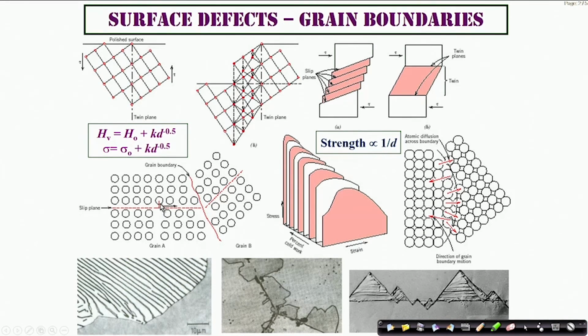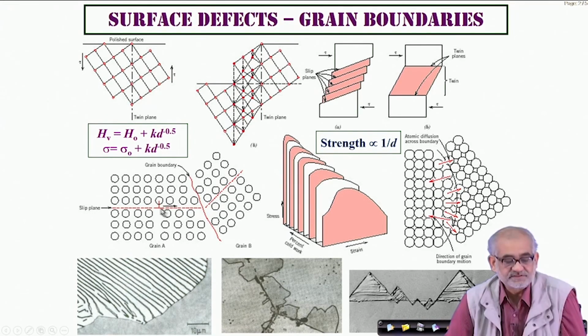So the point is, if I have such boundaries present, then a dislocation, which we just heard is the main agency required for explaining any kind of deformation of crystals, can find its way all the way up to the boundary, but then will face a barrier across the boundary because the continuity changes here, or in other words, the orientation changes.